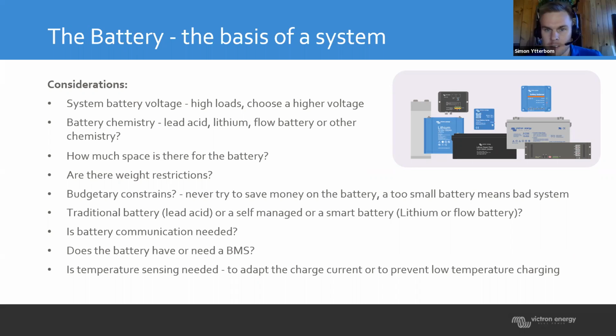So stepping up in voltage can be good, but we also want to make sure that we can work with an alternator and DC loads. So it's a little give and take there. Generally on most sailboats, 12 volt will be good enough, but if you have bigger loads, it would be smart to consider stepping the volts up to 24.